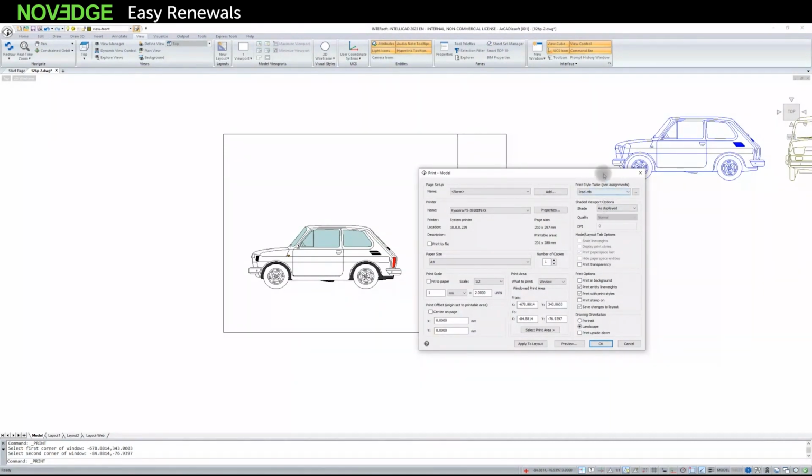When you have a transparency in the document, here it is used on the windows, you can't see it because the elements drawn here are on my solid hatch anyway. However, here I know that the transparency is used on the windows, and transparency cannot be printed together with plot styles, because in plot styles you define what color is to be converted to what color. Even if it is automatic, these plot styles do not support transparency.